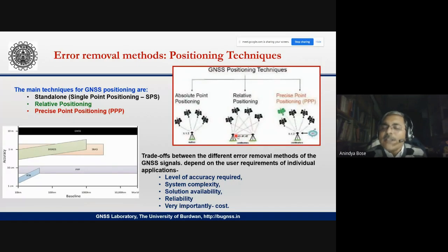So now the delta x, that means the difference between the reference and the instantaneous value, is being transmitted using radio or internet to this particular customer. This customer knows, because they have the same set of satellites and are walking a very short distance, the atmospheric conditions remain more or less fixed. Only their local condition is a bit different. So most of the errors I discussed earlier remain common. So the error that this one is transmitting to this fellow is common.